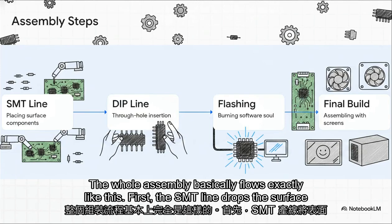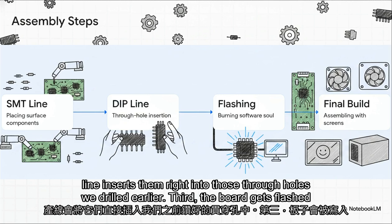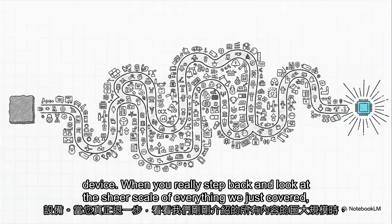First, the SMT line drops the surface components into place. Second, for the bulkier parts that need extra physical support, the DIP line inserts them right into those through holes we drilled earlier. Third, the board gets flashed with its firmware, basically giving it its software soul. And finally, EMS providers take this PCBA and put the whole shebang together with LCD screens, fans, and casings to create the final device.